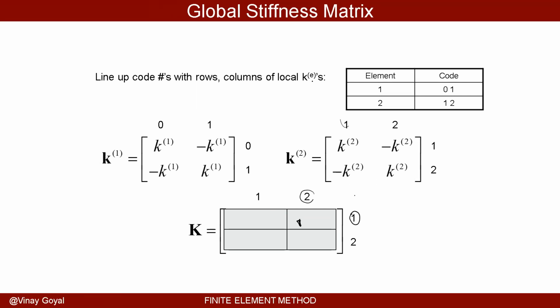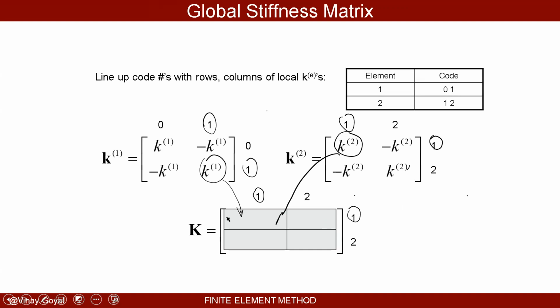So here I don't see any 2s in element number 1. In element number 2, I see a 2, 1 there. So that goes there. And then for 2, 2, for example, I don't see any 2, 2s in element number 1, but I do see it here. So that goes here. And so forth. You're basically doing a search and adding them up as you go. The only one that needed something to be added was this one, because 1, 1 shows up here and here. So those two need to be put in here so they get added up. So that's the quick approach to doing this.